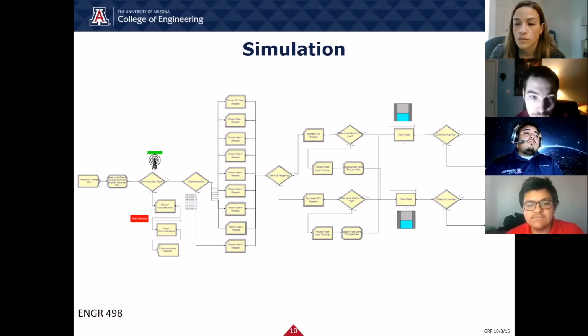There are 2 decision modules that determine whether the water level is too low or too high. These modules serve 2 purposes in the simulation. The first is to simulate the possibility that the request to increase or decrease CFS will result in the water elevation being too low or too high accordingly. The second is to demonstrate how the system would automatically readjust the gate's position to bring the water elevation at the gate to a good level. As a result, the system would send the operator an alert that the water level was either too low or too high.